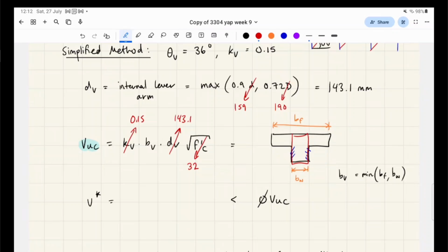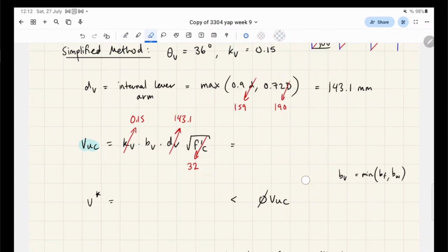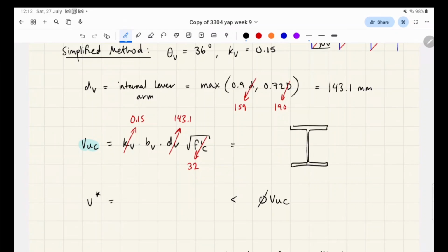Sometimes you have pre-stressed concrete like I-beams or I-girders in bridges, with pre-stressed steel, which is not in this course, but it's always in the thinner part. That's correct, and I think that's pretty intuitive as well. You've done steels, right? No, I haven't. So in steels, we have I-beams, and the web takes on the majority of the shear. So the shear distribution looks like this.